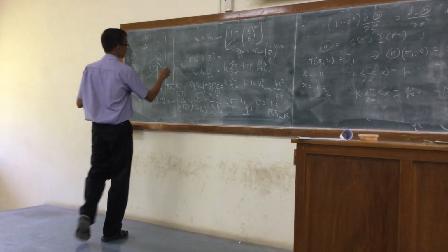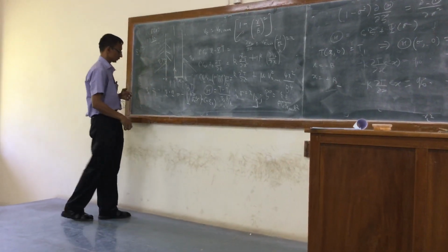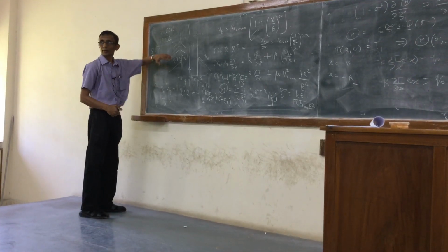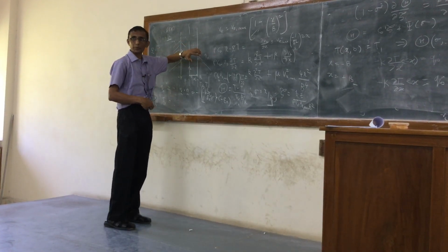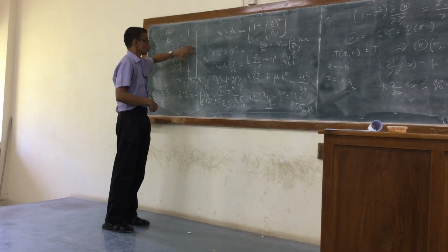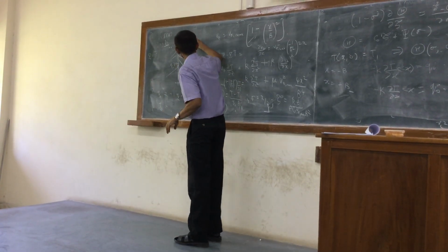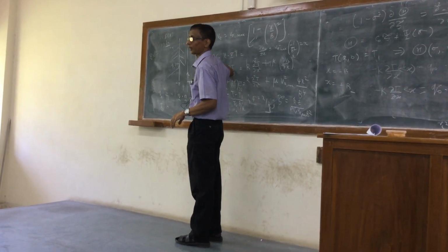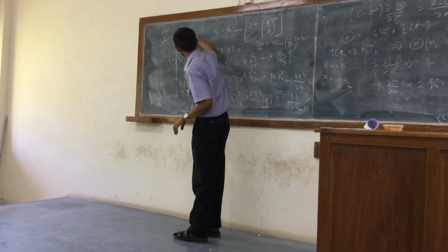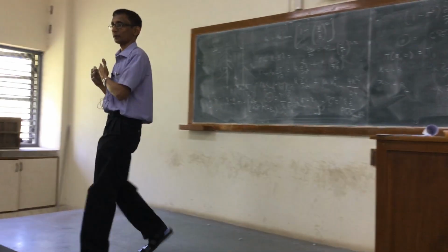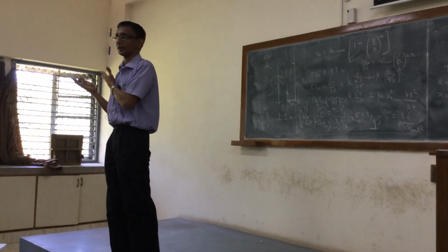Now you can easily see if I do this here, again q naught greater than 0 is coming in, so I will treat it as being heated from here also. The flux entering the surface from the outside is now being transmitted from the surface. There are two parts to the surface, and that is where the problem comes in. If it is continuous, it is always minus k dT by dx.